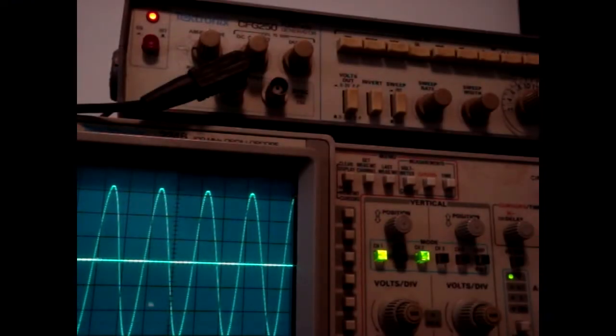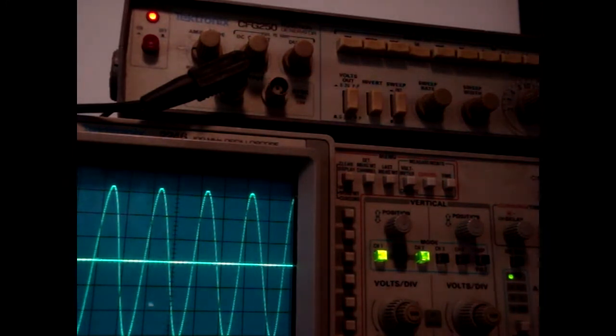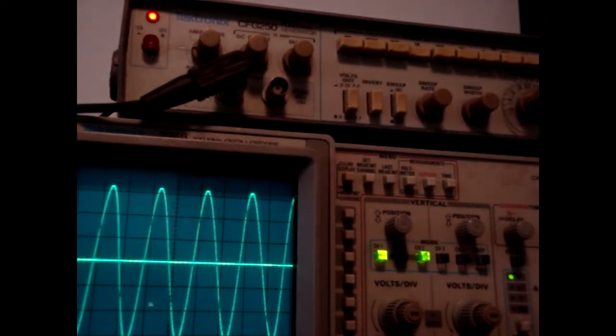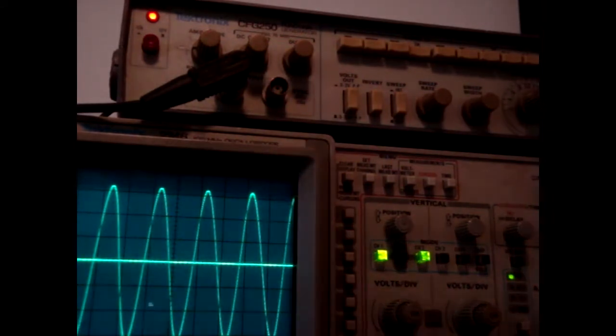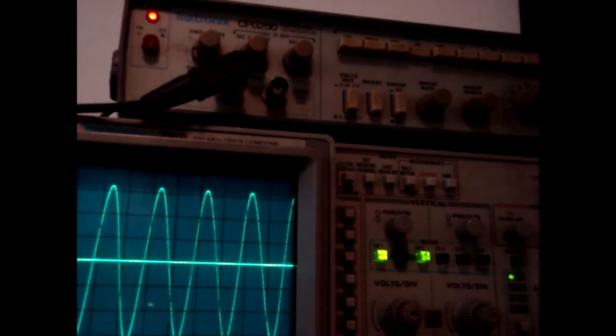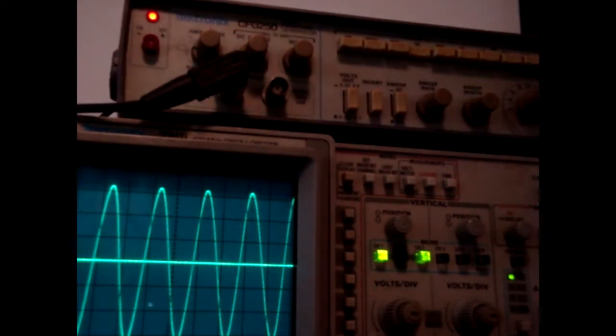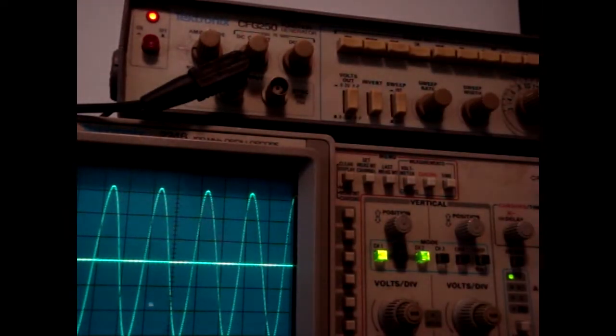Paired with an oscilloscope, a signal generator is one of the most essential pieces of test gear that you'll ever have. You can't really do it without it. It's primarily used to inject a signal into the front end of amplifiers and effects we're working on, and then we signal trace using the oscilloscope probes to see if there are any breaks in the signal or distortion or whatever. I'm going to cover signal tracing in a later video, but essentially that's how we do it.